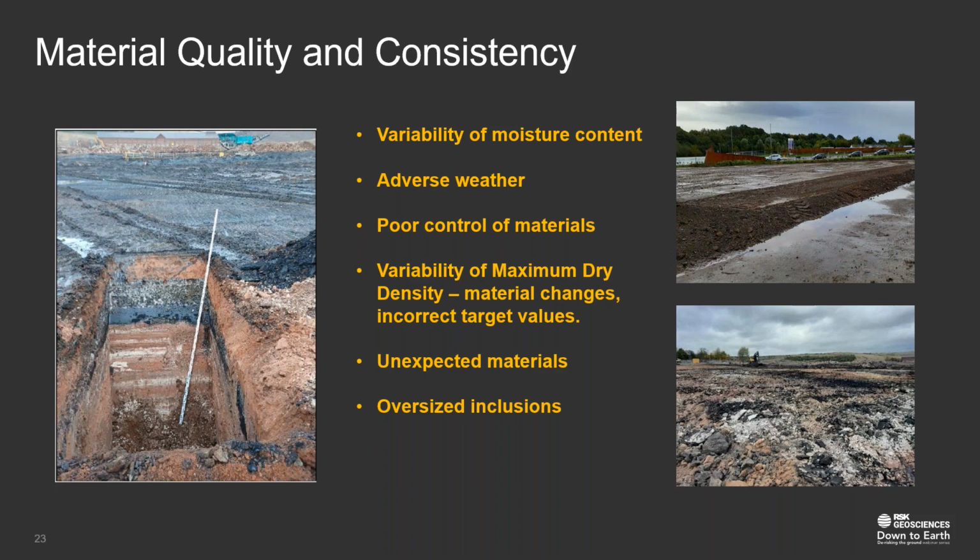That's exacerbated if you don't control the materials on site properly. You've got to look at stockpiling, sealing your stockpiles. If a material is dry enough to place, keeping it dry enough to place. Once you've placed it, making sure that it stays of a reasonable quality, designing your filling so that you've got a slight crossfall so that the water will drain off your placed material and it's not softened by the weather.